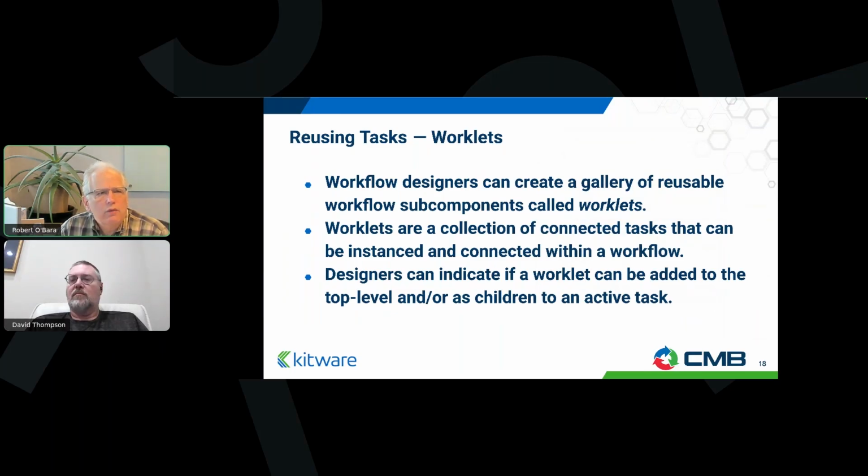Okay. In terms of reusing tasks, one of the things I should point out is that in that OpenFOAM wave tank workflow, there's a bunch of tasks, for example, controlling snappyHexMesh, merging mesh, and so forth.